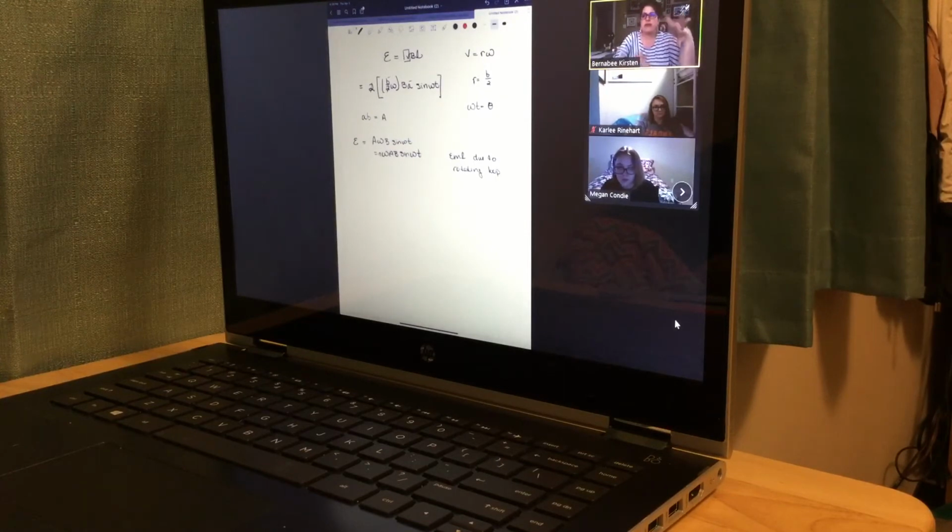So when you have a battery, it's using a chemical reaction to produce that voltage. Once that chemical reaction has been depleted, you need to run current back through it the opposite direction to recharge the battery. If I supply a current that's going forwards and then backwards and then forwards and then backwards because it's changing direction, I'm never going to be able to recharge this. I need to supply it with a nice direct current.